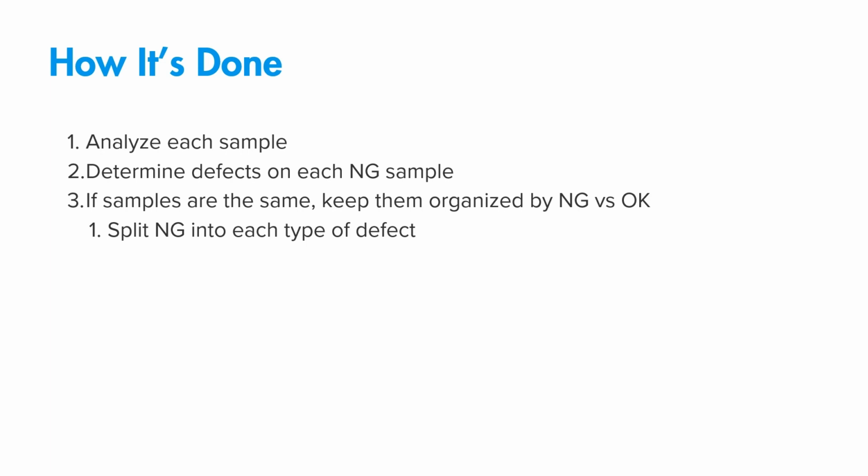If you're the end user and you're doing the testing by yourself, it's up to you to determine internally what makes an okay sample, what makes a no good sample. You can do that by looking at your process. Would our process right now call this borderline part no good? Would it call it okay? Do I want my vision system to call it no good, or do I want it to call it okay? Then define that line for yourself and use that to create the line in your vision system.